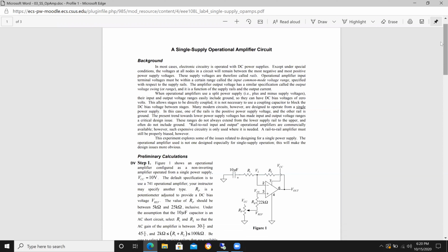So there's going to be some noticeable differences. The first one is right in the title, right? It is a single supply op amp. So why is that of interest? Well, a lot of times, think of something as simple as your remote control for your TV. Maybe it has a couple of AA or AAA batteries in it. So more than likely, it's going to have a single supply on it, like maybe a 3.3 volt supply, or a 5 volt supply, or whatever the DC is, and it gets regulated down.